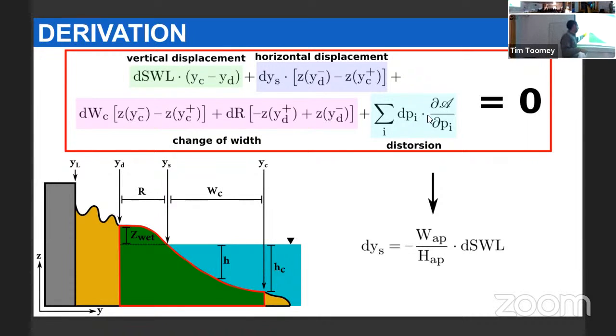So for example, for underwater bathymetry, what we call an underwater elevation map, people use video cameras, because if you are watching the incoming waves, the period of the waves and the space between the crests, so the wavelength and the frequency, define the depth because of the wave dispersion equation. So you are monitoring the waves and can know the depth beneath them.